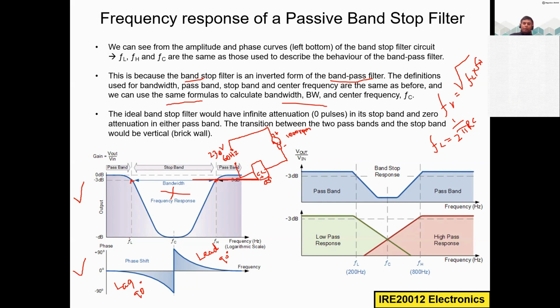Now I want to reduce the speed of this motor to half, from 1000 to 500 RPM. In this converter circuit, I have some kind of rectifier that converts the AC into DC. Then I also use pulse width modulation, reducing the pulse width and controlling the amplitude.